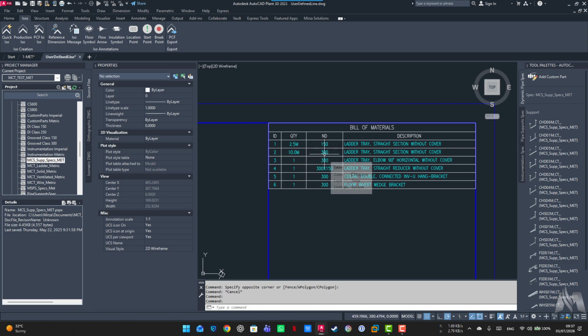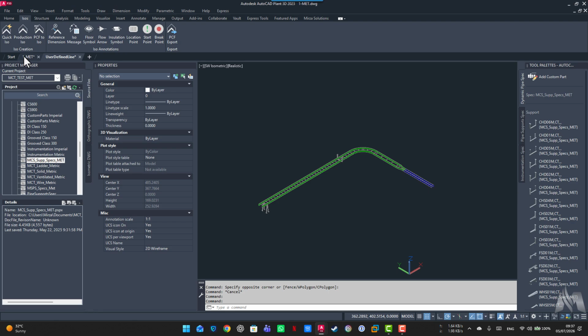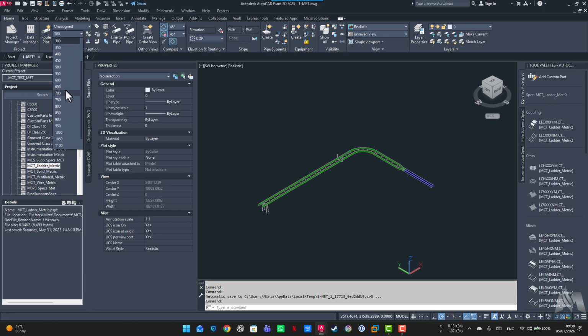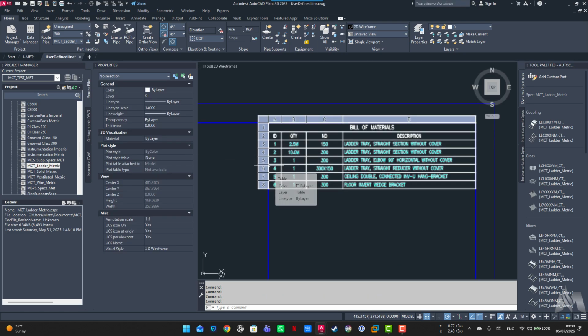That's because by default, AutoCAD only looks for the ending or the size parameter, which we select from over here. If I go to the settings section again, which we select over here. Okay, so this is not the behavior that we wanted. But for simple purposes, if your cable tray system does not change very much in the parameter section, this is good. But if your cable tray system makes parametric changes along the run, then this will fail and will not give you the required results.